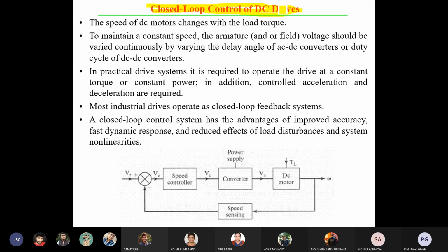No, it's not possible. So sometimes we have to amplify the current level or voltage level, and sometimes we have to do isolation. I will also come to why isolation is important. For amplifying the current level, we incorporate a BJT. Suppose the power circuit has a power BJT, and in your control circuit you amplify using a totem pole configuration or Darlington configuration. I hope you can recall that.